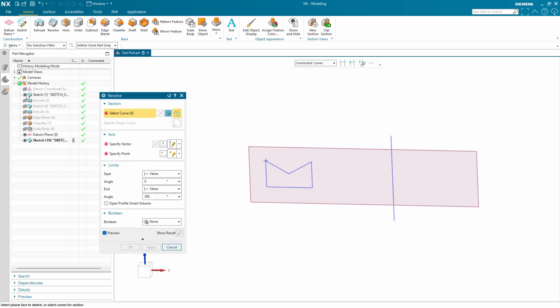I want to go back to that original sketch, and this is the curve that the Revolve tool is asking for. Because if I had hidden this inside of an extrusion, I can't access this as easily. So if you need that original geometry that I do now, that's the perk of keeping your sketches non-consumed by your features.